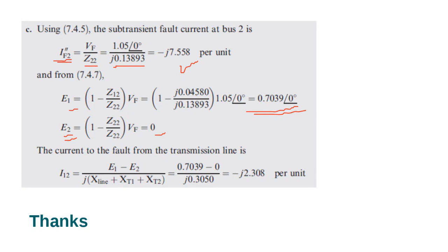You see now the importance of Z bus and how to determine it from Y bus. And then I12. Now see, it is not to 1. I12 means from 1 to 2. So therefore, you will use E1 minus E2, over the impedance of transformer 2 and transformer 1. So what will be the current? This will be minus J. And this negative J here is the angle, because of this J here at the denominator. Now this concludes sections 3 and 4 from your textbook.